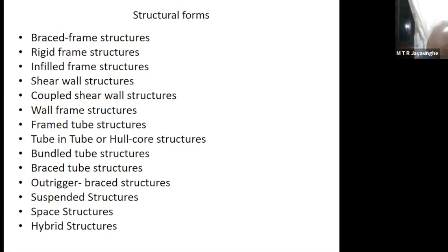Generally, pre-stress slabs are very efficient only when the spans are like 8 to 10 meters. They are very efficient because you have to use a minimum thickness of about 180 to 200 millimeters. Generally, you don't go for a thickness less than that. So when you use 200, then when you increase the span to about 8 meters, 9 meters, you need only 220.